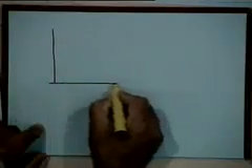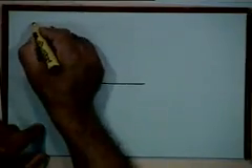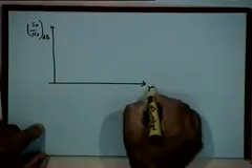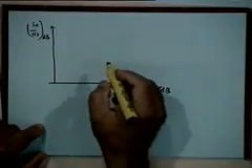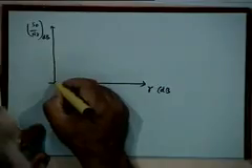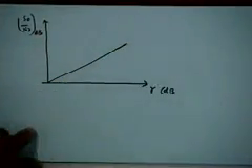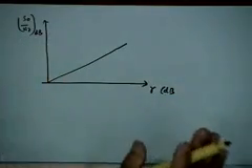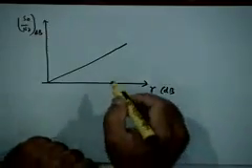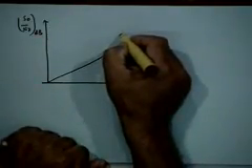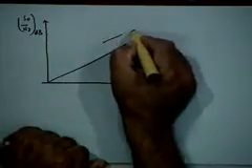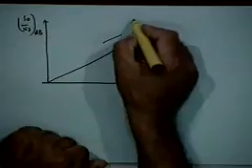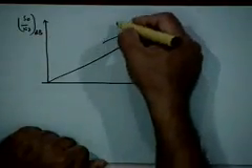But let me draw the picture for you in terms of the SNR curves. So if you look at the SNR curve at the output in terms of gamma, right? I'll use the baseband case as a benchmark. Remember, in the baseband case, output SNR is equal to gamma, right? Always this has been our benchmark, right? And what we learned that for angle modulation, as you increase the modulation index, right, your output SNR increases, right?